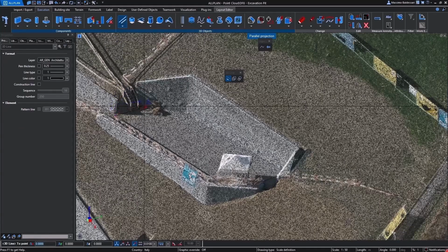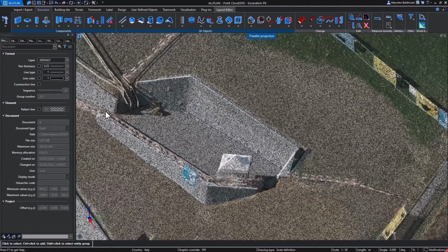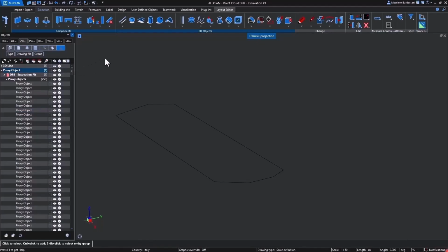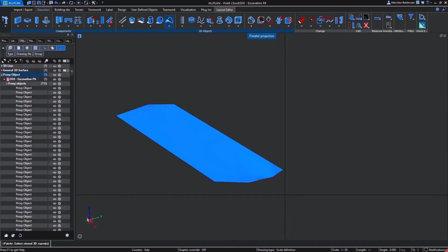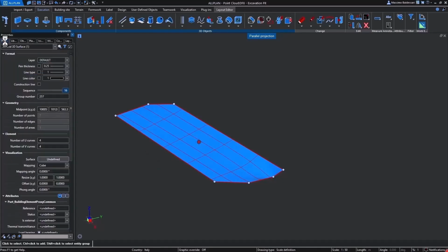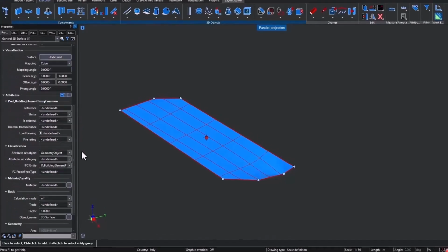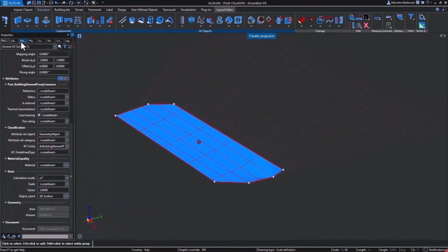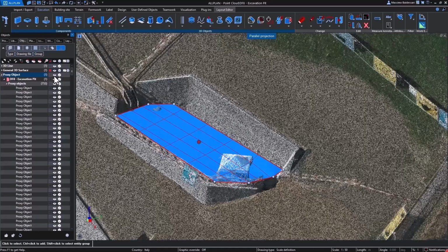Why am I using 3D lines and not directly a surface? This is primarily because the specific points I am going to align probably do not all share the same z coordinate. So the unique ability to directly generate these sophisticated 3D lines, which can later be converted into a smooth surface thanks to the very practical patch function, allows you to effectively manage even incredibly complex surfaces. What can I do with this complex surface? For example, I could check its total area, and right here I find that it measures approximately 108 square meters of total exterior surface area.